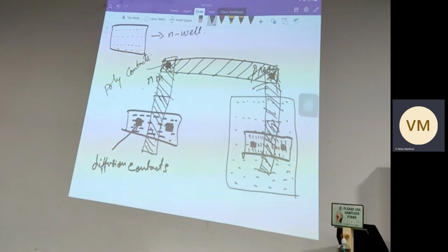Sometimes what happens is on this first floor, second floor, we are running the metal, right? I want the connection to go and connect to some other part of the circuitry. So I may need the help of another layer, because on that layer I cannot bypass certain devices. So how to go up and then come back, right? The metal which I have used for the first time in my circuit, in my VLSI, can come on the first floor or the second floor, but the lowest layer on which I first use the metal is called M1.